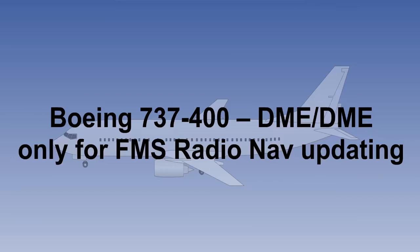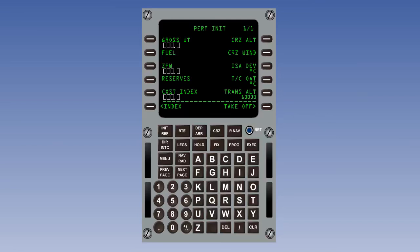On that model, there was no GPS at the time, and the VOR-DME option was discarded as being too inaccurate. Therefore, for the Boeing 737-400 only, the only source of radio navigation updating is the DME-DME option. This concludes this lesson, and with it, our study of flight management systems.